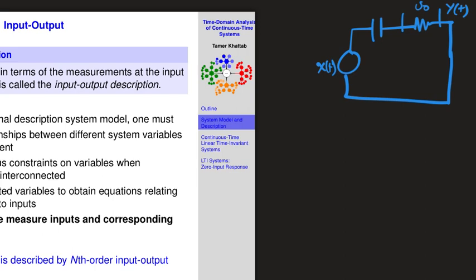So you start analyzing every single component. You know, for example, that across the capacitor, if you have a certain voltage Vc, what's the relation between the voltage and the current on a capacitor? Yeah, the current going through the capacitor, IC, is equal to C dVc by dt. So the current going through the capacitor is equal to the capacitance multiplied by the derivative of the voltage, right?